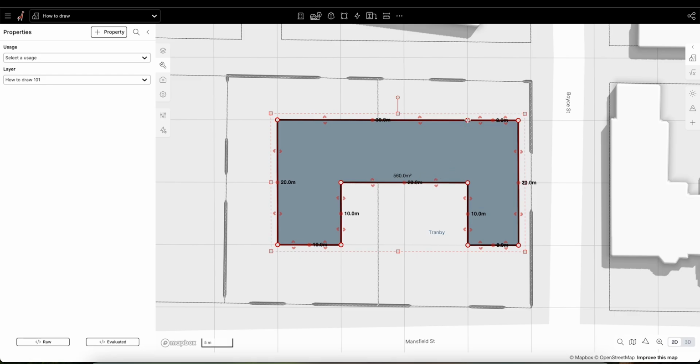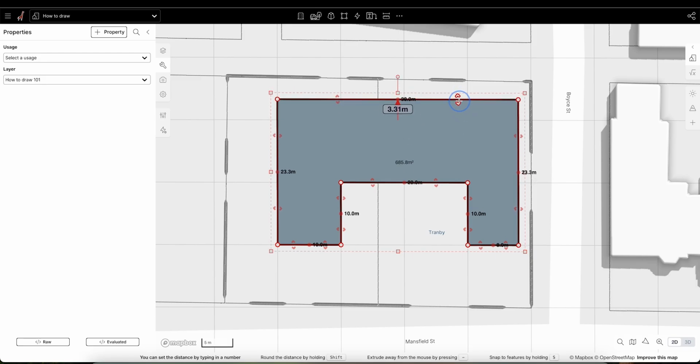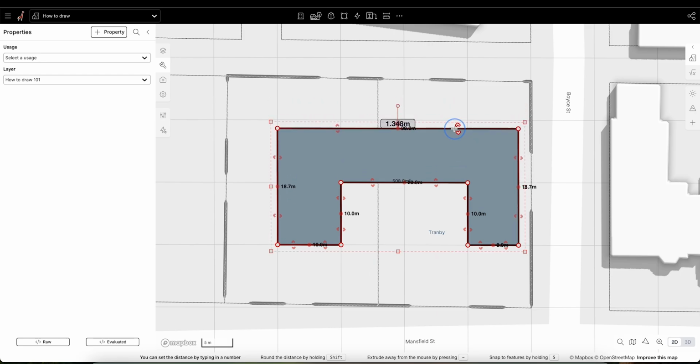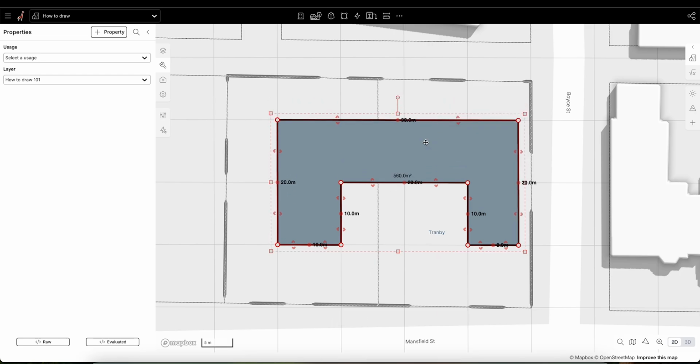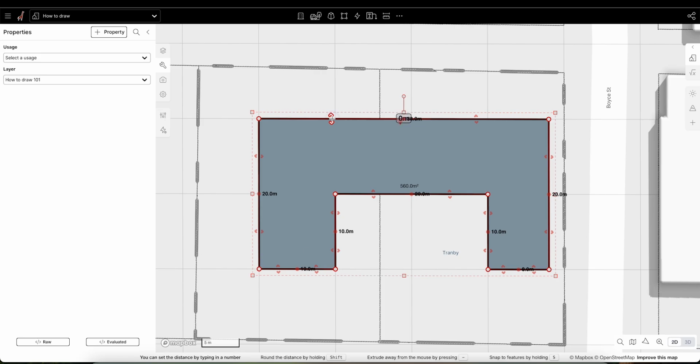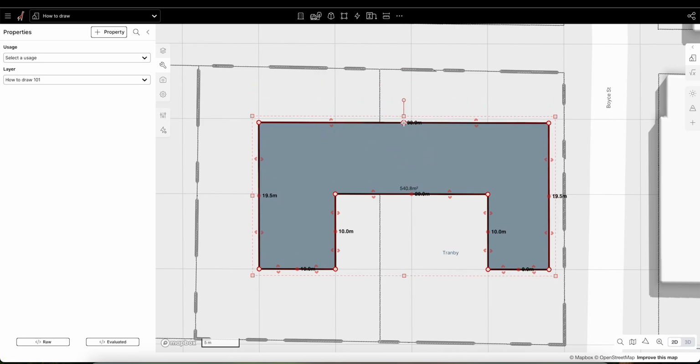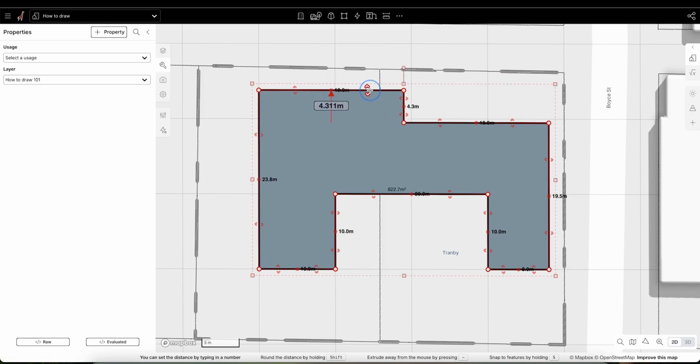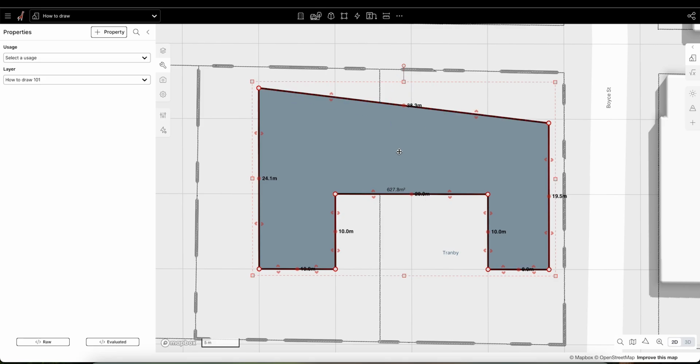We can actually just remove those nodes. So if I click on that, that disappears, and we can control that in one singular plane. So that's quite nice. But we can add segments to that geometry as well. So the same with the rectangle. We're obviously using the polygon here, but with the rectangle it is much the same. And any geometry really in Giraffe, we have this editability to sort of push and pull the form. We can segment the form. So if I click that little plus button, it adds a node, and now I can drag that independently and just as easily remove them as well.